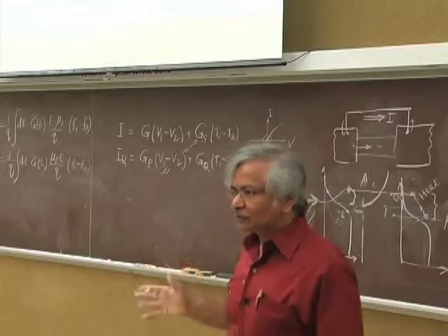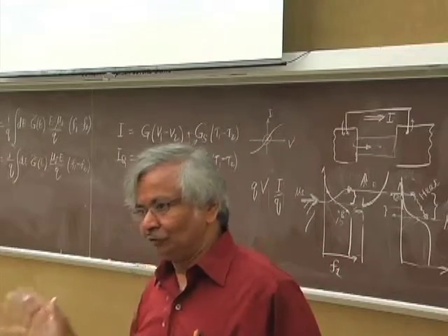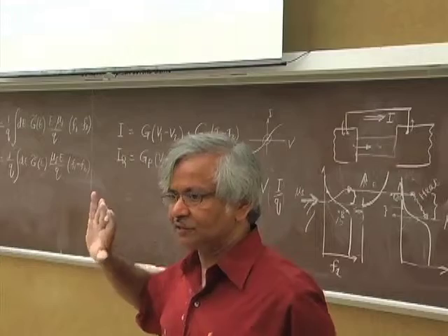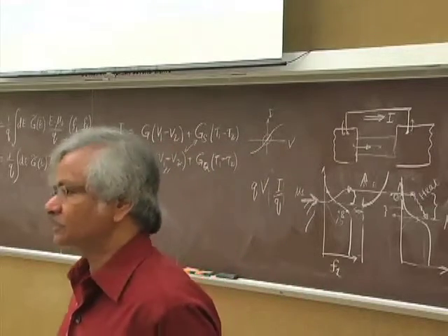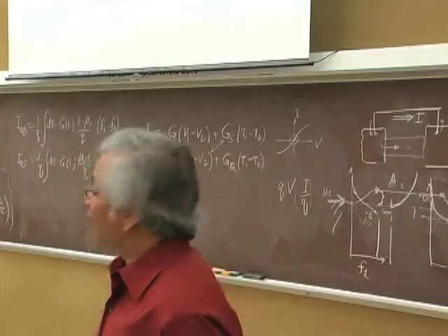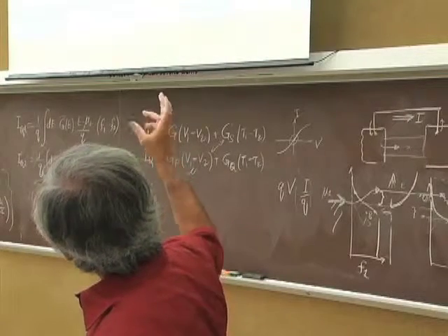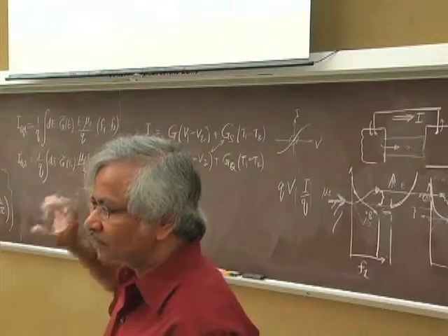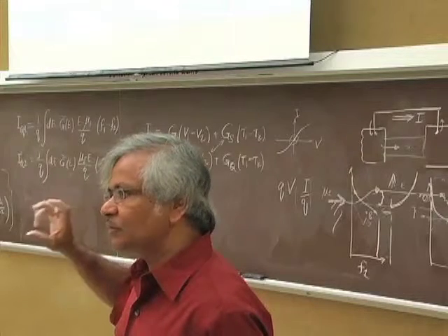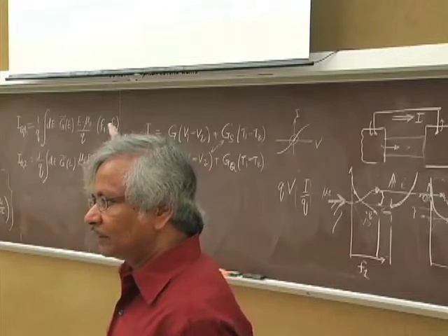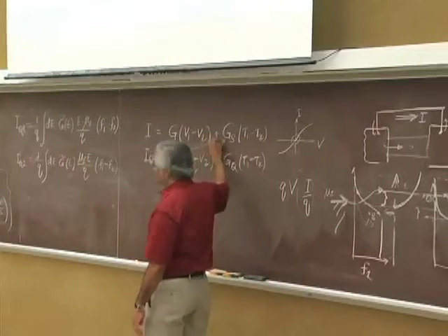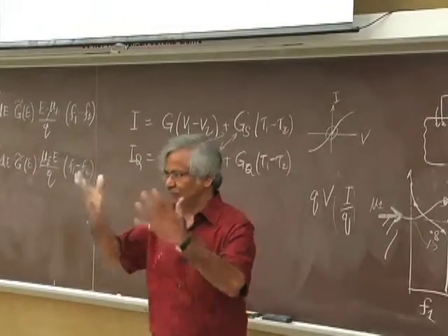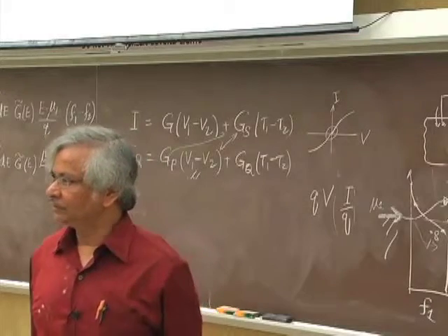And again, none of this is anything that's not known. In the literature on thermoelectrics, this is all consistent with exactly what you'll see there. Yeah, that's called the Onsager relation. Actually, this particular relation between the Peltier and the Seebeck is called the Kelvin relation. But the fact that these coefficients are similar is a special case of the general Onsager relations.